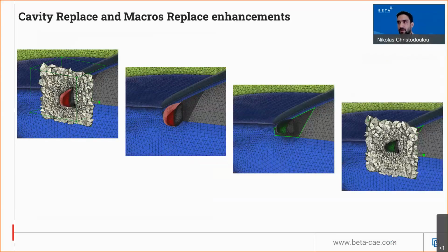Regarding now cavity remeshing, it is now possible for the user to replace a meshed area of the model with a new unmeshed geometry. The unmeshed geometry must, however, belong to PIDs that are already loaded in an existing surface mesh scenario, so that ANSA applies the specific mesh treatment to the new geometry. Of course, after the surface mesh, ANSA will proceed with the volume meshing.